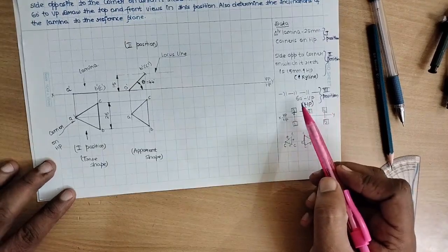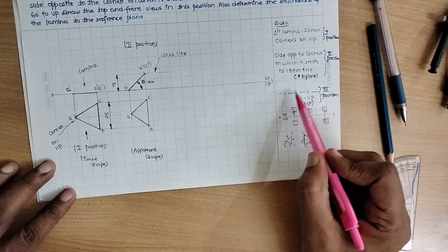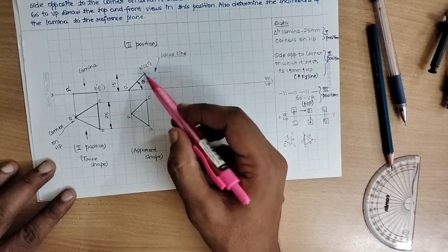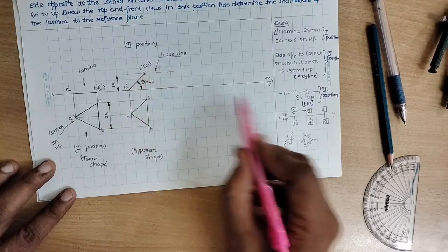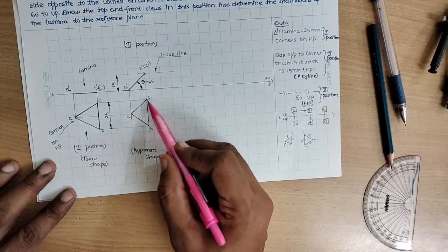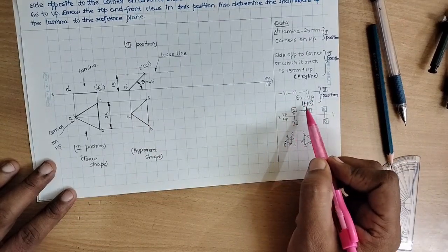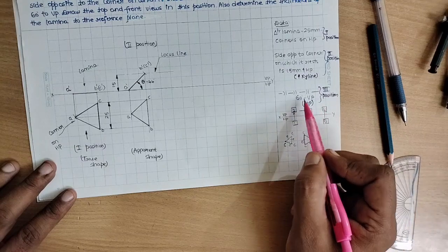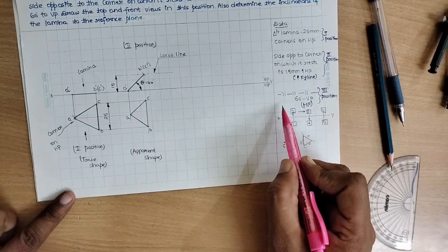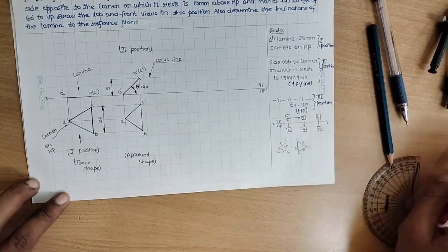The last position now. The same side opposite to the corner on which it rests. At the time of taking the data, I just used it as a ditto, the same thing. The same CB. Here it was 15 mm above HP, but now the same CB is inclined at an angle of 60 degrees to VP. VP inclination should be shown under HP. The inclination may be anything, 60 degrees or 40, 50, 30 degrees. Whatever the inclination is, you need not worry, the procedure remains the same.